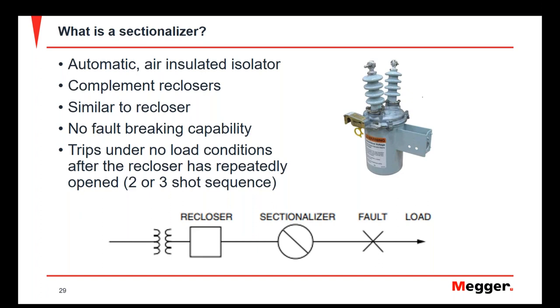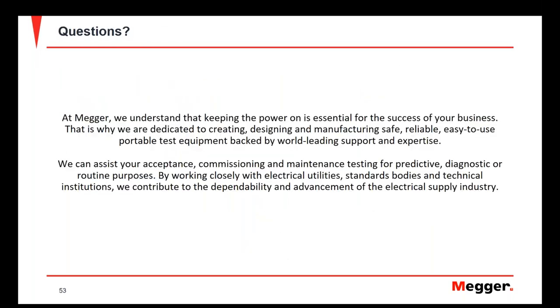Okay, so these are some specific applications, and I would say that there are very few three-phase current injection systems in the market, and if there are, they might not cover a big range of current. One solution, depending on the instrument that you have, is to use three of those instruments and connect them to three different phases.